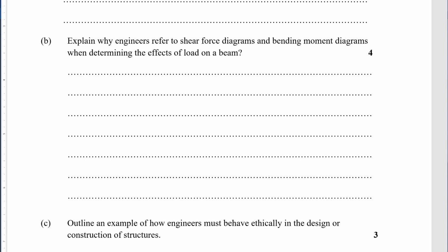We certainly can design for the amount of reinforcing we use or the size of a steel beam, so the size of the material. We might decide that timber isn't strong enough for a beam here. We might need to say we need to put in a concrete or steel beam. So that's where we talk about material type. Another thing that came up in discussions with HSC markers is we might change the design, or we might put in new supports at a different location based on that.